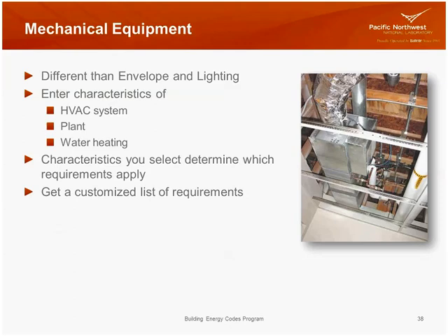So for the HVAC system, that really refers to a secondary HVAC system, which could include controls, fans, terminal boxes, radiators, coils, and packaged HVAC equipment. It's not the primary HVAC system components. If you were to choose plant, then you're getting into primary HVAC components that you would define, which could be a boiler, a chiller, cooling towers, and pumps.